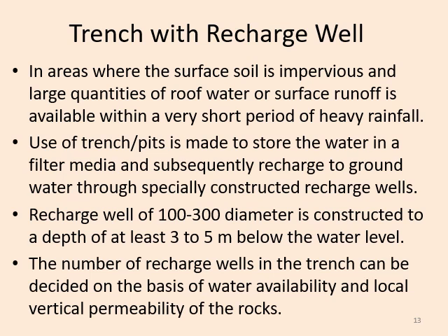The number of recharge wells in the trench can be decided on the basis of water availability and local vertical permeability of the rocks. So the number of recharge wells which we have to construct will depend on the water availability and the vertical permeability of the rock, because the water is going down.